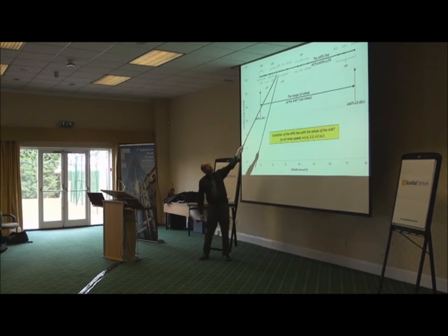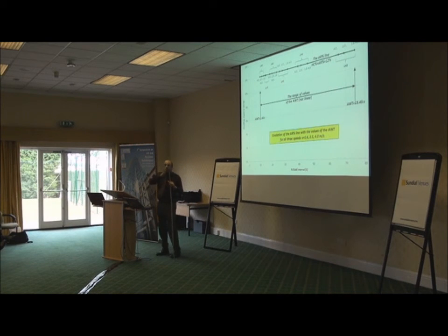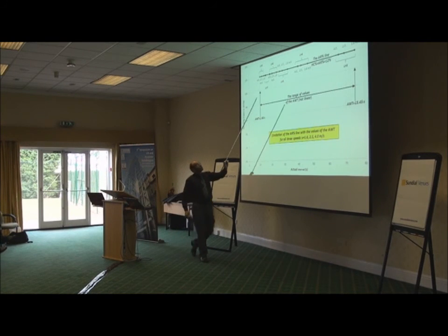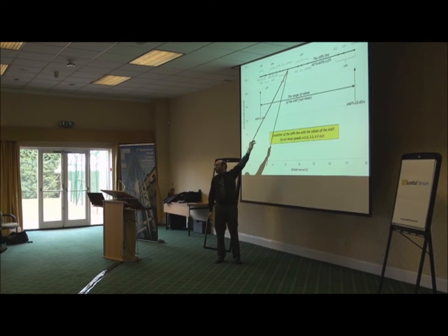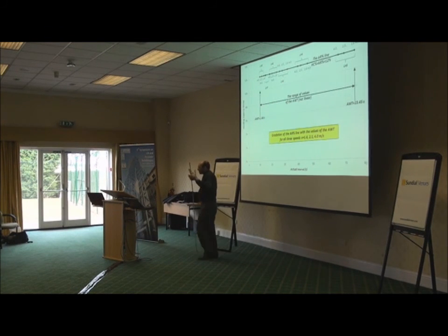And you can see how there's no overlap until very late on between the speeds and the number of lifts. So you get to the top speed for a number of lifts, and then to move next, you have to increase the number of lifts and then drop down again to the lowest speed. So 4 lifts at 4 meters per second is worse than 5 lifts at 1.6 meters per second. Lifts are much stronger. Obviously they cost more if you increase by 1 lift.